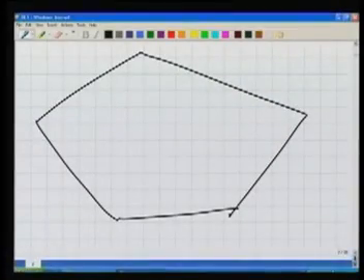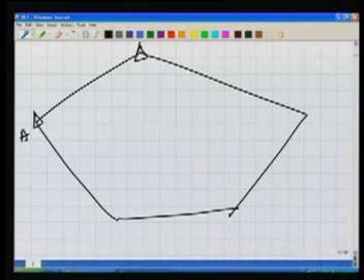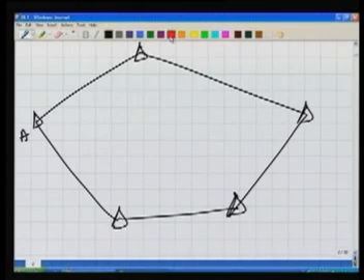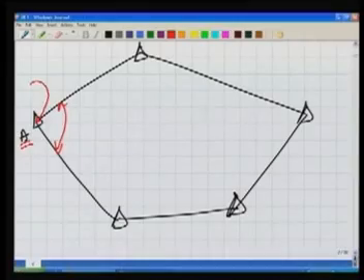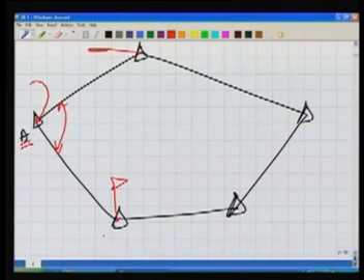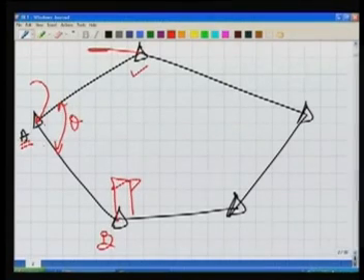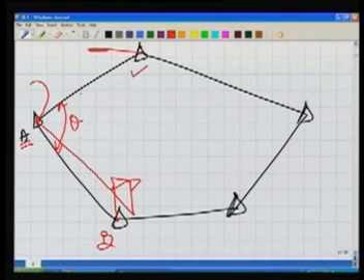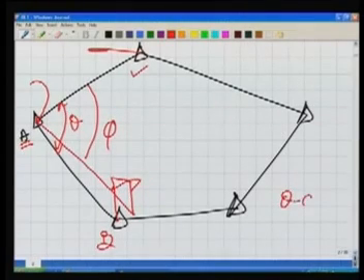The meaning of the centering error is, for example, if we have to carry out a traverse like this, then these are the traverse stations or survey stations. If we are measuring this angle here, in order to measure this angle, we need to put our theodolite so that its vertical axis is exactly over this point A. Then we say the instrument is centered. Not only the theodolite, we also have to ensure, if I am using a ranging rod here and another ranging rod here, then the base of the ranging rod should also be exactly at point B and over here. If the base of my ranging rod is slightly shifted, then instead of measuring the angle theta, I am measuring the angle to this particular point. Let us say this angle is phi. So theta minus phi is the error.